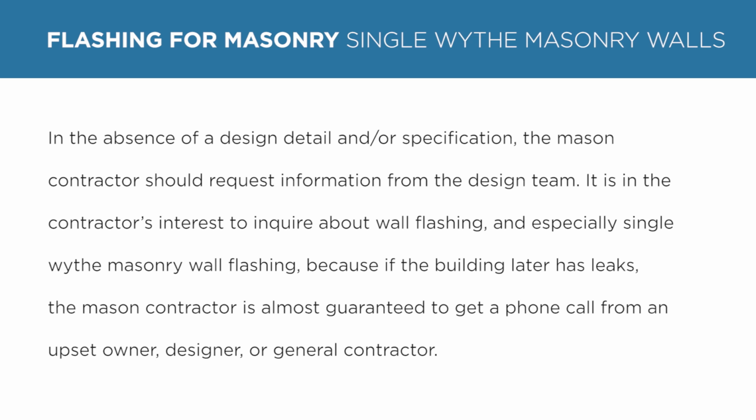It is in the contractor's interest to inquire about wall flashing, and especially single-width masonry wall flashing, because if the building later has leaks, the mason contractor is almost guaranteed to get a phone call from an upset owner, designer, or general contractor.